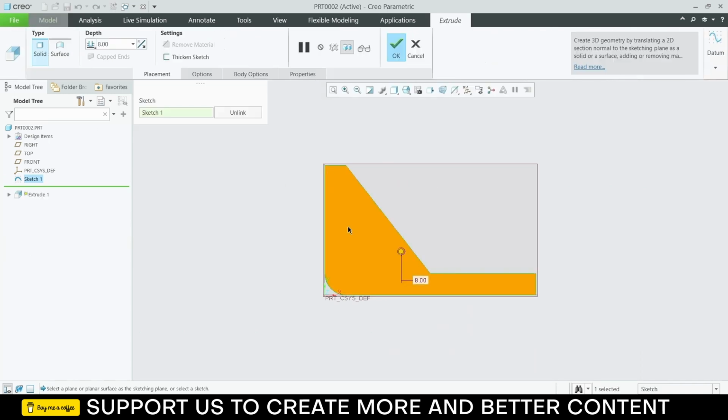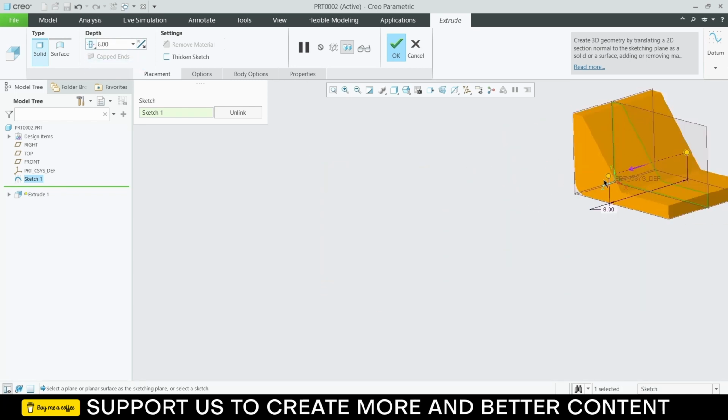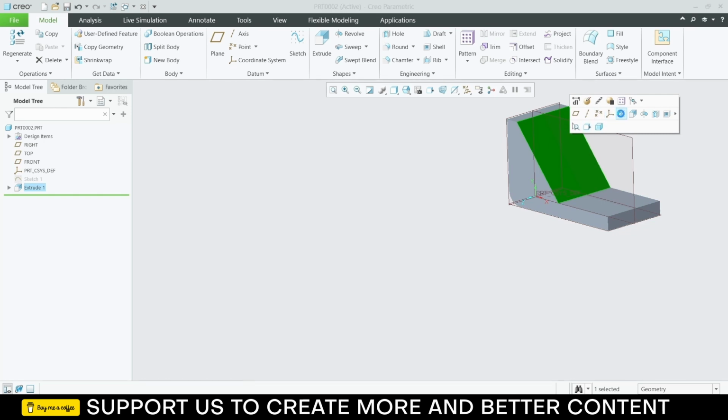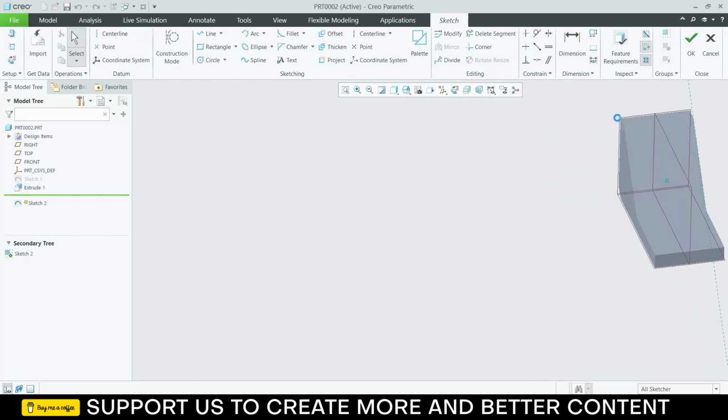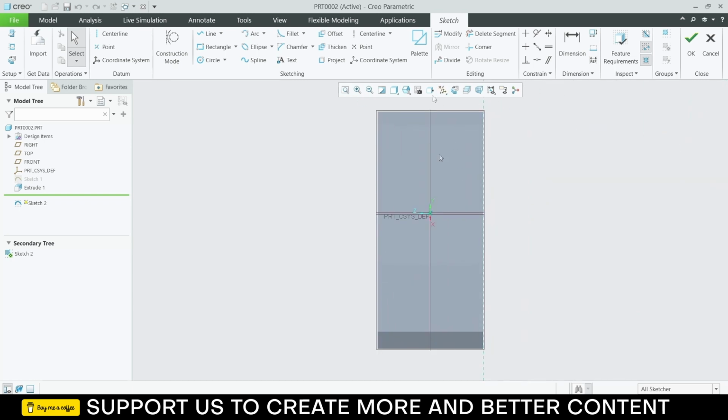and click on extrude. Make sure that you this time select symmetric so that when I select the face to make a circular hole it will be easier for me. So symmetric and its width is 5. Click OK. Select this face, click on sketch, shift N for normal to the screen to the view. Click on this so that it will become this way.